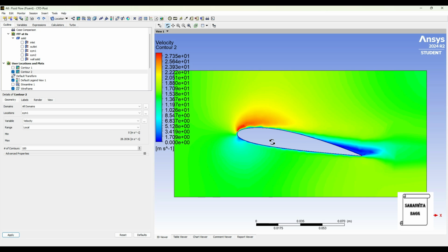Now here the value of lift that we had got was higher and the drag was low. So that means that the aerofoil is going to experience an upward motion. The lift is more. So the positive angle of attack anyway shows that the aerofoil is moving upwards. And the angle of attack should be between 0 to 15 degree, because above 15 degree the aerofoil gets stalled. So what we prefer is between 0 to 15 degree only for this angle of attack.